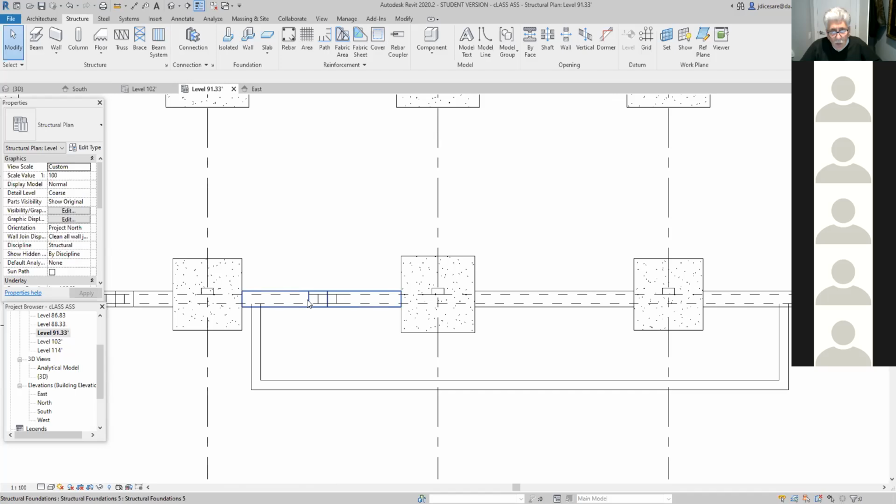Guys, see where you made your step footing in this wall. If you want to keep it nice, you can try to make the step footing in this wall right in line with the step footing from that wall, so you can step it down there, with one exactly beside the other. It's up to you. It doesn't matter. If you don't get exactly this point here, it doesn't matter as long as you're approximately in that area. The footings don't have to be exactly lined up, but if you want, that's where my step footing is in this wall. And in this wall, I have exactly the same one here.